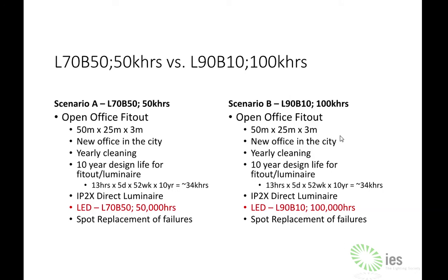Let's improve things. Let's make this LED better. Let's use the quality fitting. L90 B10 100,000 hours. That's the only change. We've upgraded from an L70 B50 50,000 to an L90 B10 100,000. We've paid a lot more for the fitting, and it's going to have that European feel. We'll appreciate that.